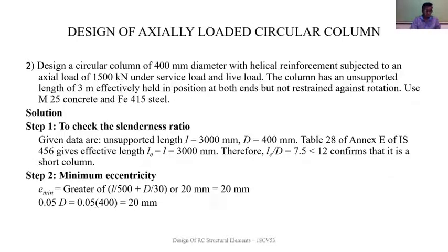Earlier observations of several investigations revealed that the effect of confinement holds good in the elastic stage only, and it gets lost when the spiral reaches the yield point.